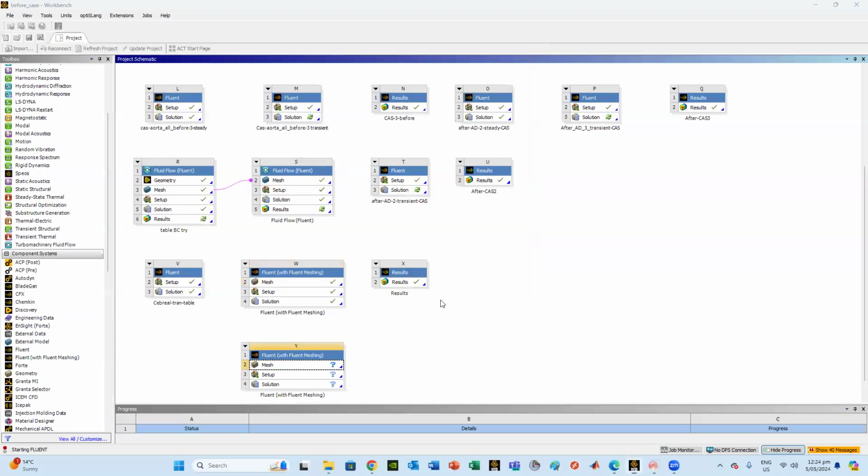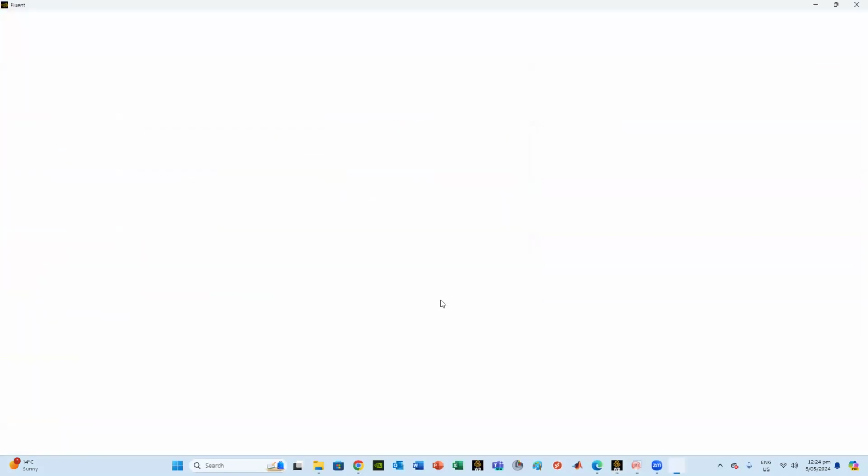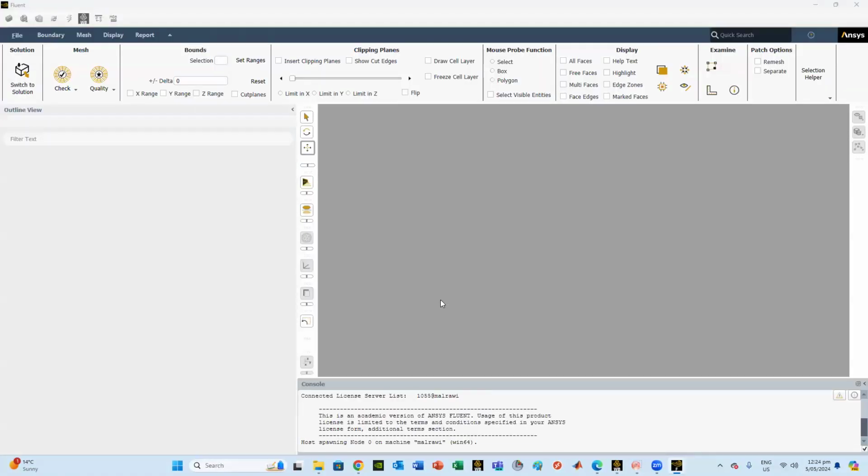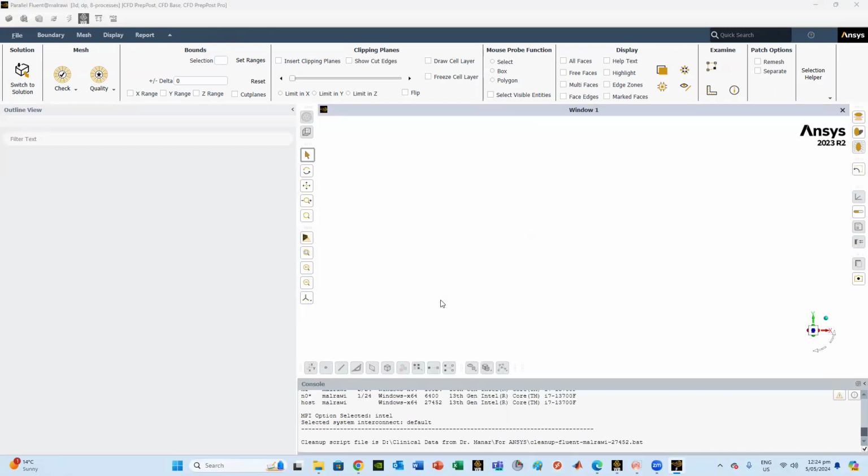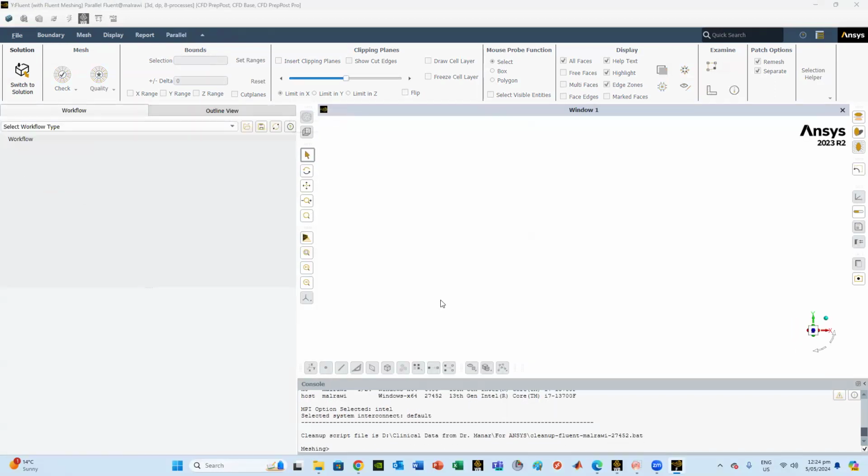the Fluent simulation first to bring the mesh file, and then based on the mesh file, I can set up the boundary conditions. And also I'll show you how to read that text file, which is converted to a profile. And as well, how I can change my model to non-Newtonian using the K omega SST turbulence model. So I open that file.